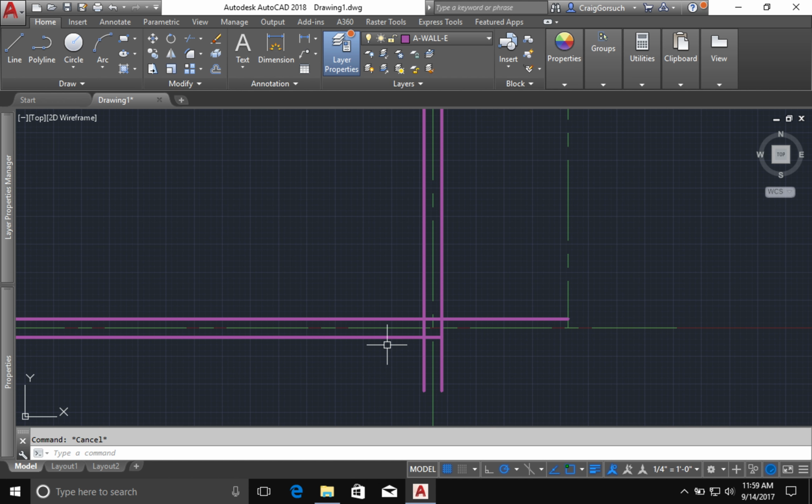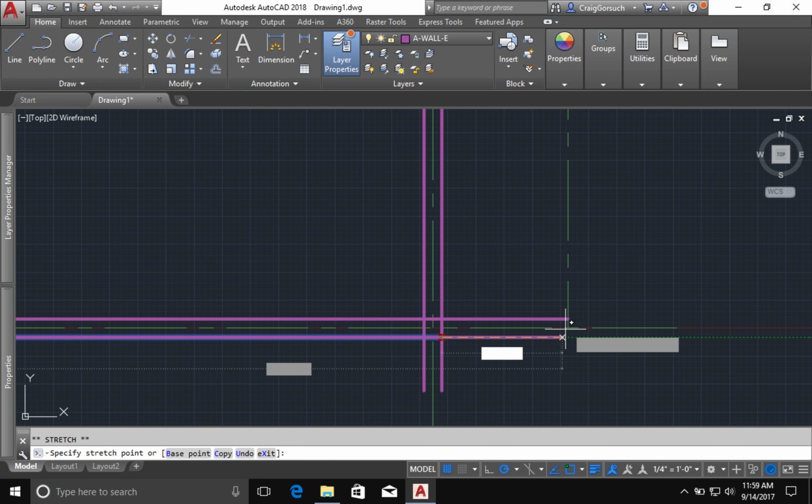I need to back up on this one because I did it differently, and I want to show you. So I selected my line, and instead of hovering to get this menu and then selecting an item in the menu, I'm just going to left click right on that grip, and that's actually going to start my stretch command. And what I can do now is if I hover over this endpoint, I can get my object tracking up so that my object tracking is lining up vertically, and my modify tracking is aligned horizontally, so I have an implied intersection here. If I left click now, then it's all closed up.